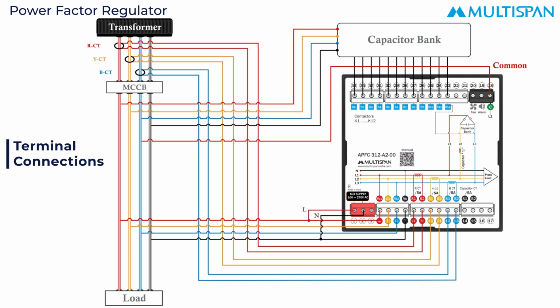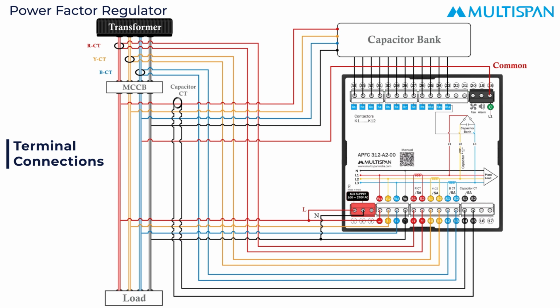Then, install a capacitor CT in any one line of the capacitor bank and connect it to the instrument's terminals 14 and 15 at S1 and S2.